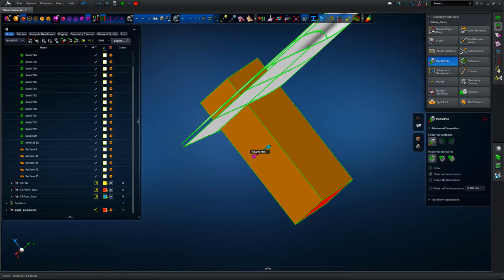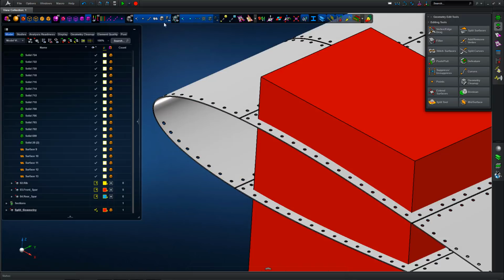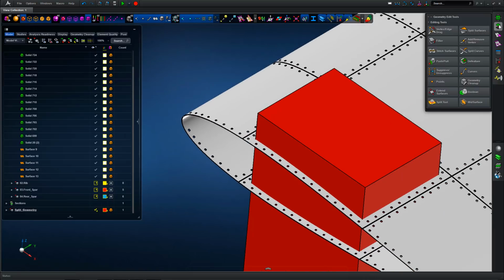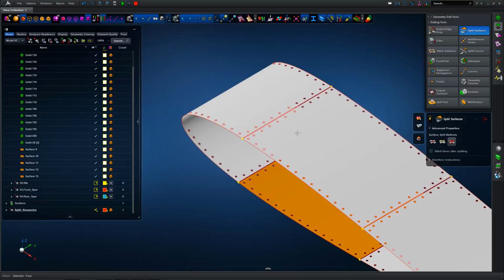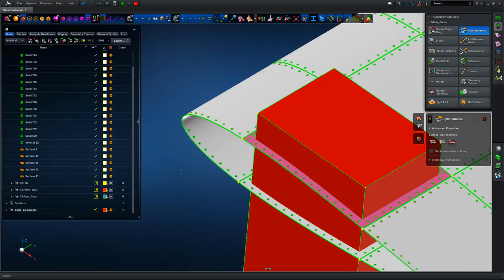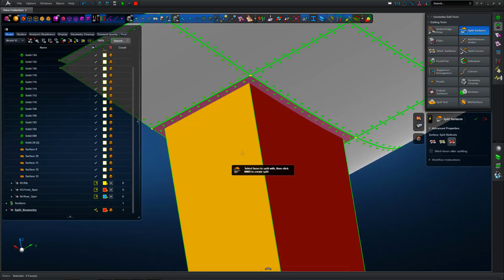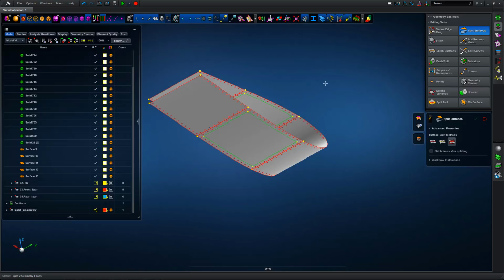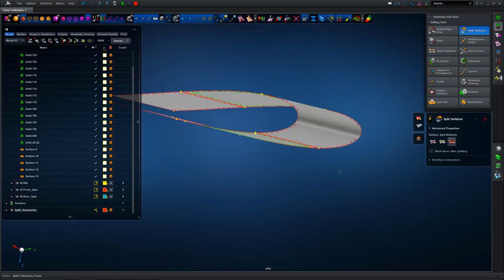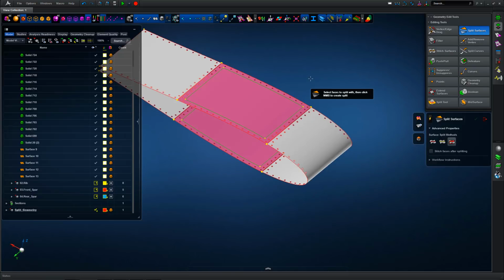So we're going to shrink the overall three-dimensional solid based on push-pull and a negative 40 dimension, or shrink in the surface normal direction, and then we're going to simply hide the surfaces, hide the solids I should say, pick the surfaces that we want to split, and then put the solids back in view and use the split surface tool to highlight the faces that we want to split the underlying wing surfaces about. And again, by hiding the surfaces we can see the splits with the green shed edge lines that we wish to split the surface about.